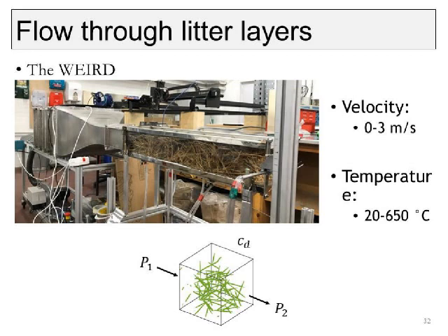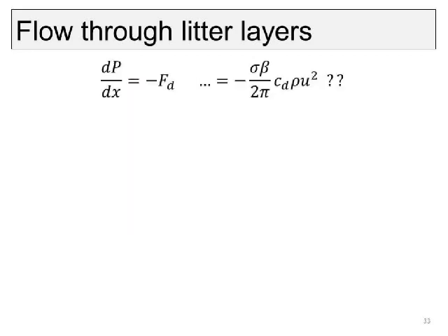And this might start to look like a pretty poor representation of an actual wildfire, what we see in the field, even what we see on the table. But there is a really big benefit in terms of the modeling and understanding the physics. And that's because we've simplified this scenario so much that we've actually been able to reduce basically to one equation, which says that the pressure loss, the pressure drop that we have through that wind tunnel is just going to be a function of the drag force in our fuel bed. And when we go and simulate at the large scale, that's something that we have to know, what's the drag force of our fuel bed. So this allows us to go directly to that and just investigate this one equation.